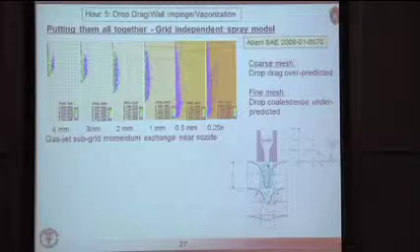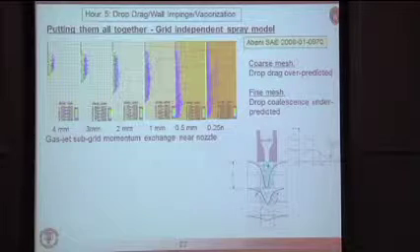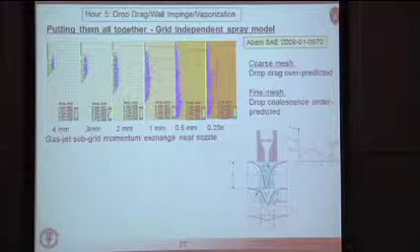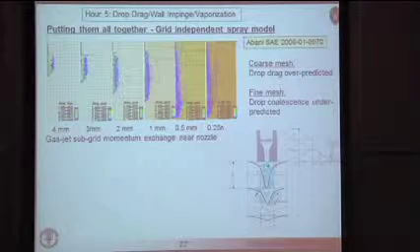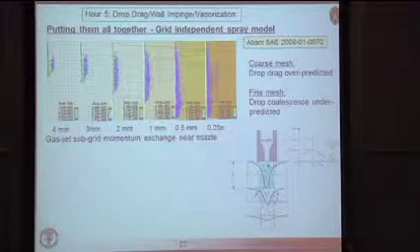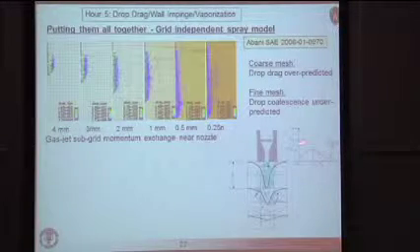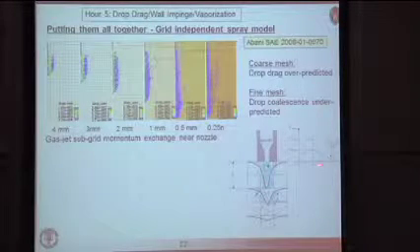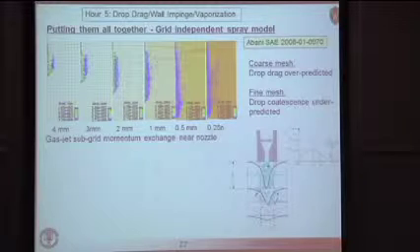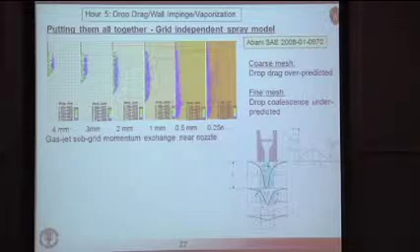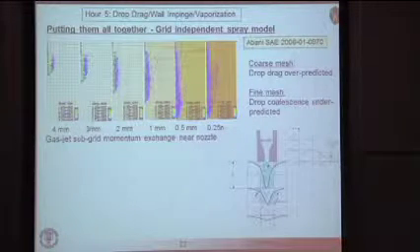So to get around that, we have one more empirical model that we've introduced, and it allows us to maintain these coarse mesh sizes, which allows you to do practical calculations. And that is, we assume that when the droplets are injected, they essentially set the gas in motion as though we had injected a gas jet with the same momentum as the liquid injection. So we can go to gas jet theory and